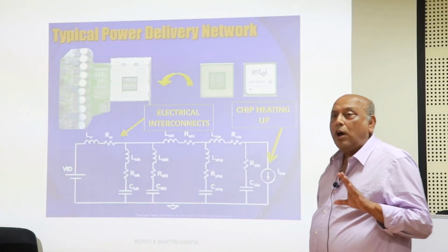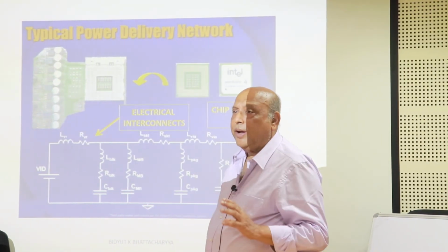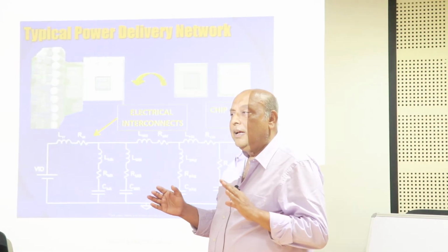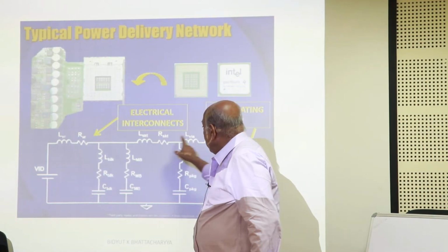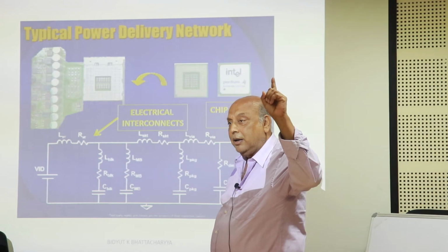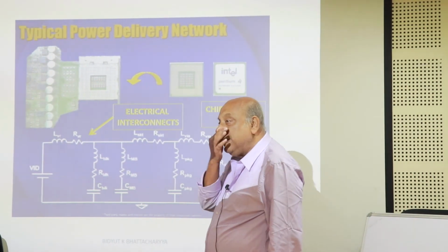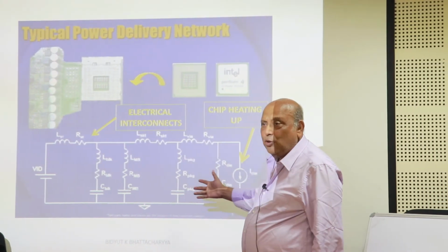So people have worked every day to massage every one of those components, every one of these connections, to make it the best and the lowest resistance and impedance. You need this one smaller, 1.6 picohenry. Remember the number. So all this should add up no more than 1.6 picohenry. And there are many ways they do it. I don't want to go through the circuit simulation.